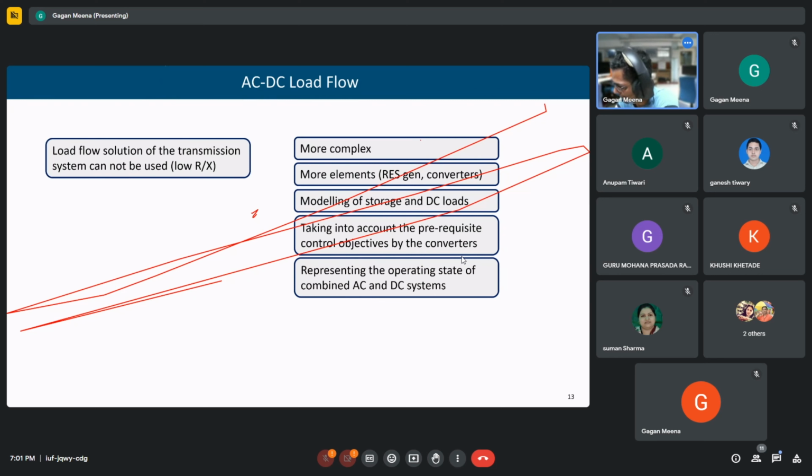Generally, when we do power flow studies for a transmission system, what type of load do we consider? What is the assumption for load type? So what type of bus is a load bus? It's a PQ bus, right? So it is assumed that the loads are constant power type for the transmission system. But in a distribution system,